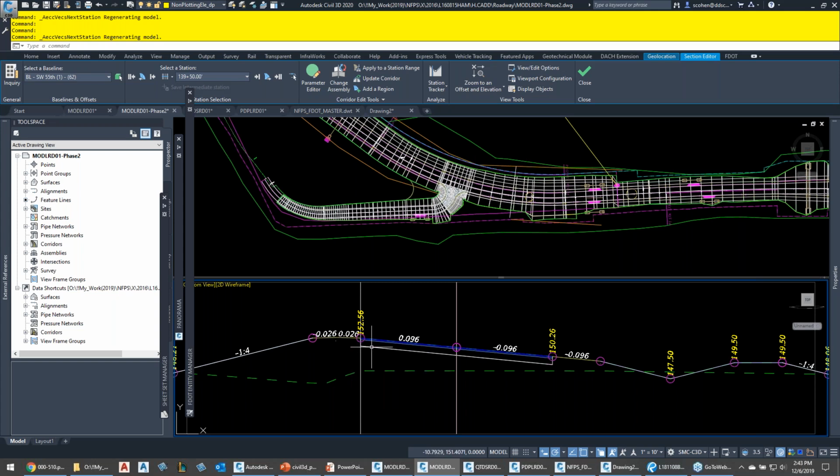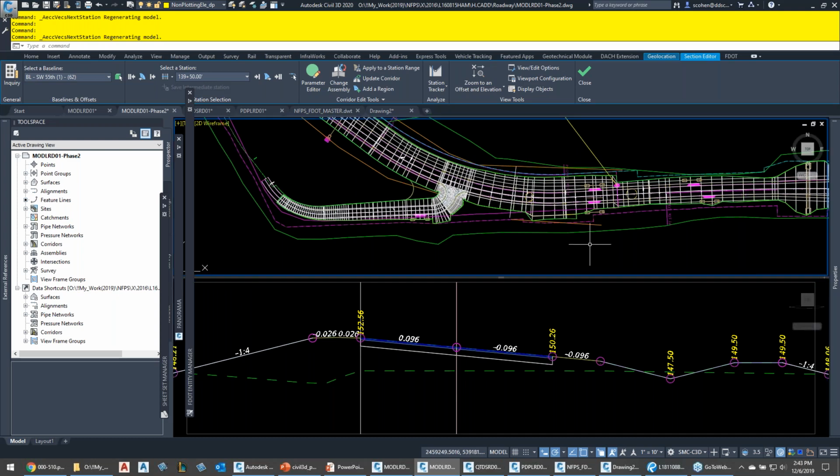Actually, no, that is right. That's 7% difference. I take that back. That's 7% difference. So that actually works just great. So again, you can see that this kind of functionality, you can't get that with Civil 3D out of the box. The DOT Sub Assemblies are just really useful, and this makes life a lot easier to work with them. Okay. Again, use your tool palettes to find them, and then you just add them to your assemblies as you need to. Okay.